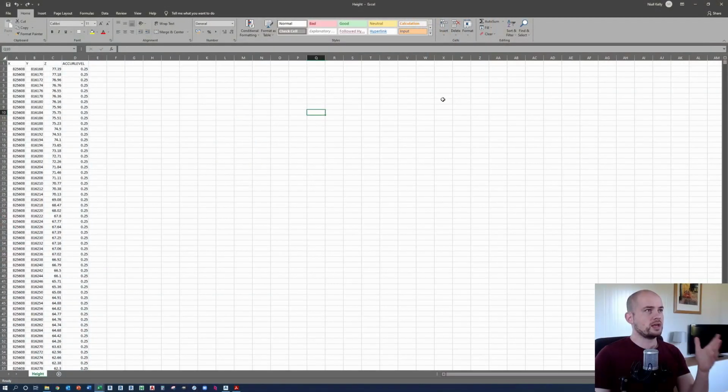All right. So for step one, the first thing we need to do is to format the Excel document in such a way that Civil 3D can draw down the point information, okay? So looking on screen here now, you can see the file received. This is a point data spreadsheet that is derived from a Lidar exercise whereby the Lidar maps the ground and just gives you the value of the point information, okay? This file has in excess of 10,000 points, okay?